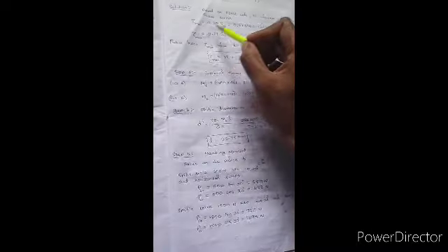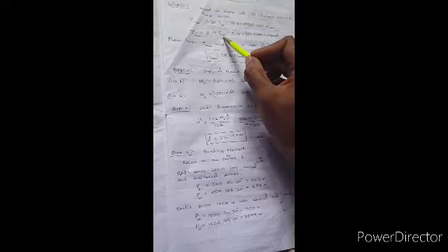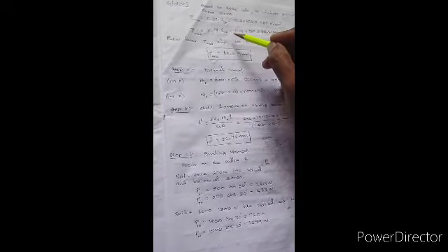But they have given both values, so we have to find the tau max value two times. Using SYT we got the answer as 180. Using SUT we got the answer as 68.4. Whichever value is lower, we have to take that value. Comparing 180 and 68.4, 68.4 is lower, that is SUT. Using SUT we got the lowest value.